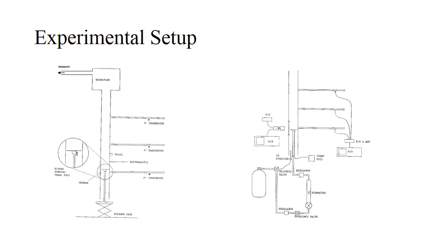On the left is a diagram of a Rijke tube showing the burner located approximately 1/4 of the way up the tube, as well as 3 piezoelectric transducers located at different positions along the length of the tube to record the acoustic pressure fluctuations throughout the tests at these different locations in the tube. The transducers are attached to points along the side of the Rijke tube via long, thin tubes that help protect the transducers from the heat in the Rijke tube.